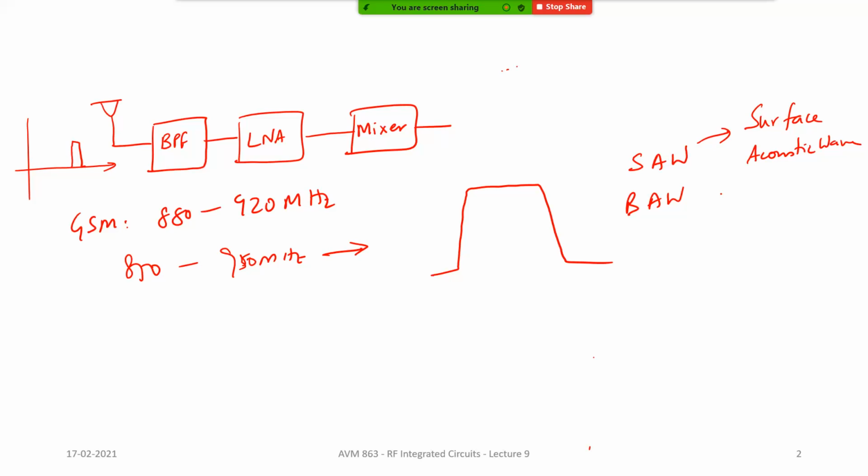That's the point. Now these filters are typically passive devices, so they do not have any gain. Typically they may have some loss. So the insertion loss, I hope you are familiar with this term, insertion loss. That is, what is the loss of this particular element? It can be, let's say, around 0.5 dB or 0.7 dB, or let's say some 1 dB, something like that. Different manufacturers, different designs will have different values.